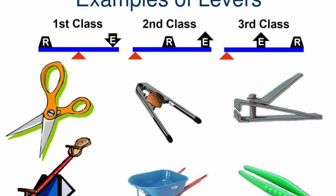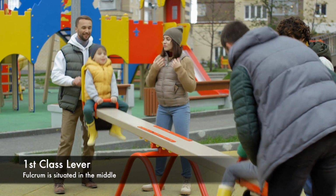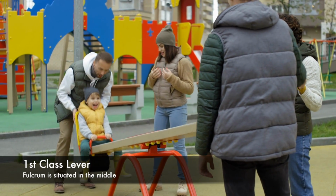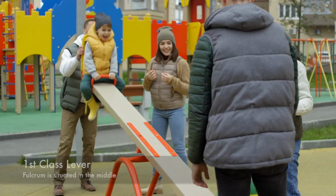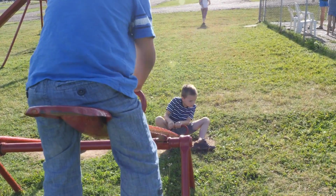Let's take a look at a few of the different levers there are. There's first class levers, second class levers, and third class levers. In the first class lever, the fulcrum is located between the load and the effort. An example of a first class lever would be a pair of scissors or a teeter-totter.